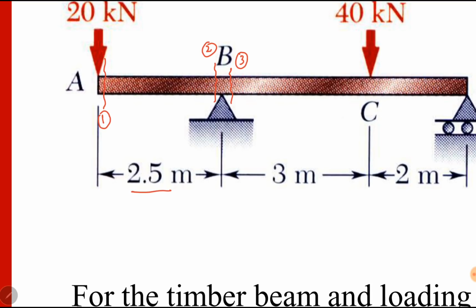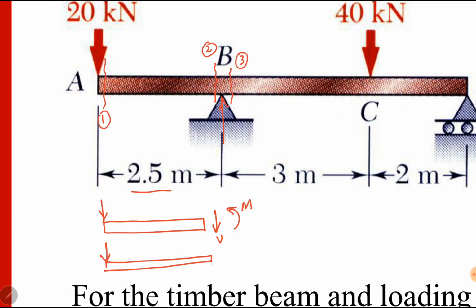But if we section the beam at 2 and we consider the left side, there is no reaction force on the left side of section 2. It is on the right of section 2. Here will be shear force and bending moment, which are unknown. But if we consider section 3, again it is of the same length, but on the left of section 3, there is a reaction force RB. So this is the difference between section 2 and section 3. The force RB is not included if we section the beam at section 2, and it will be included if we section it at 3.